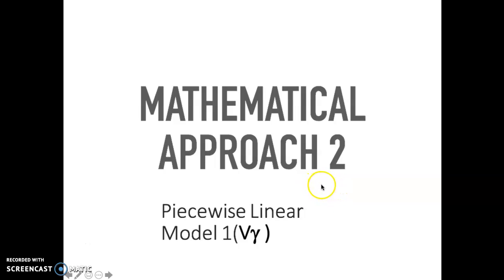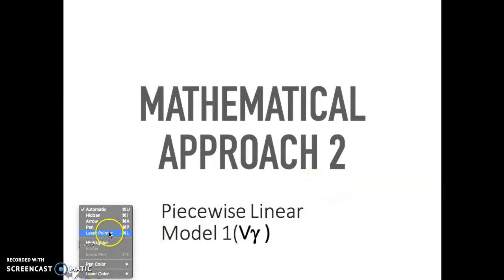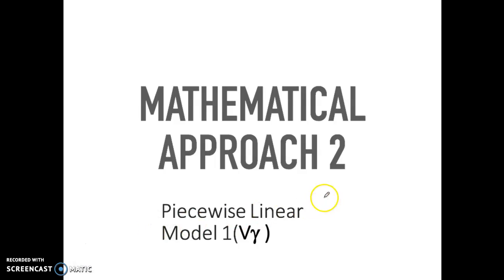So let's continue our chapter. In the previous video, you learned about DC analysis, where we have the direct approach, but it's difficult to solve. So we go to the mathematical model. Number one is the ideal model. What does ideal model mean? You're going to replace your diode with a short circuit, which means here your V gamma is equal to 0.